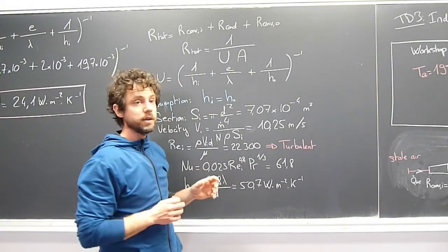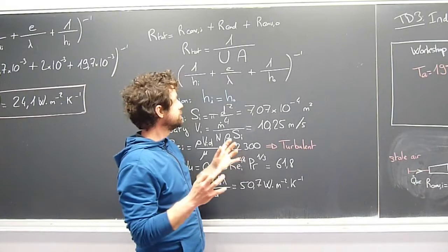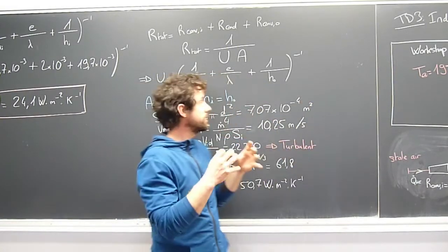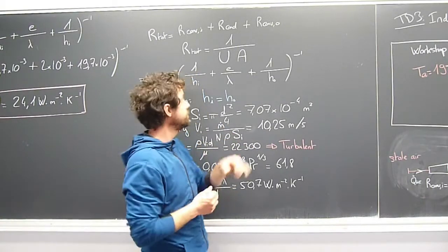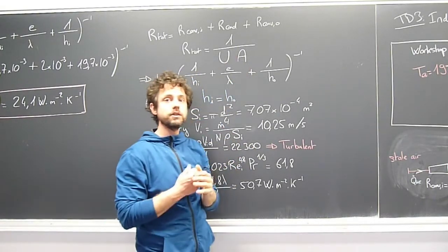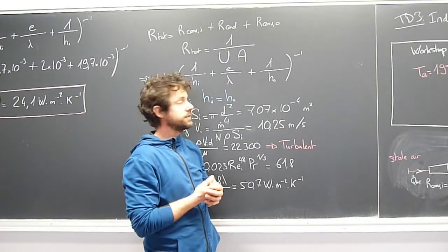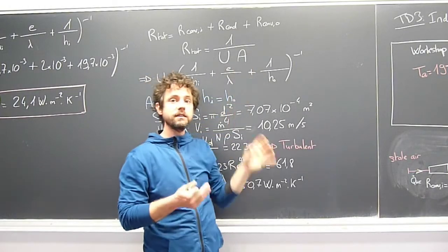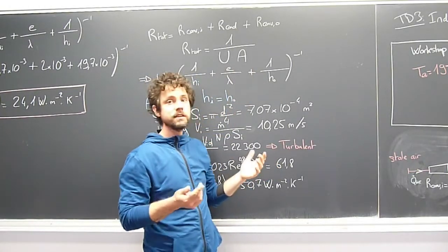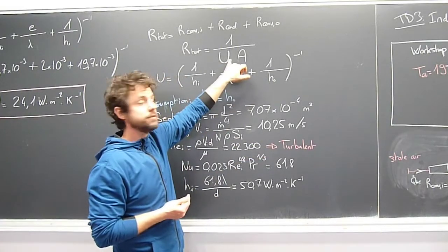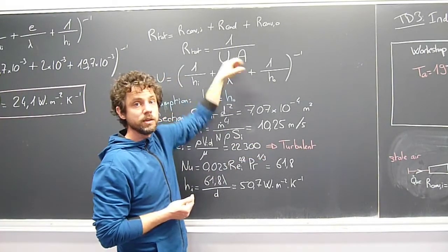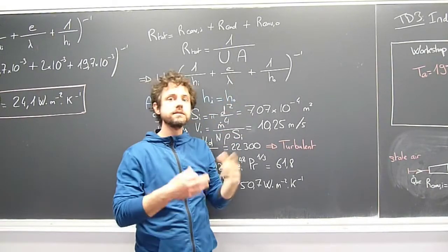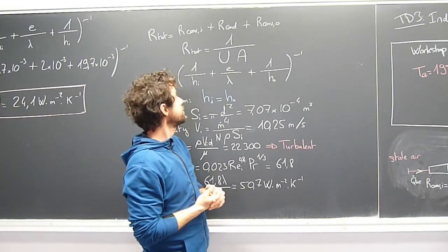And that's a way to put all the different types of heat transfer and thermal resistance into one single coefficient, U, that is homogeneous to a convective heat transfer coefficient. Here, because we consider that the inner and outer surface are equivalent, we only have one U. We don't have U_I and U_O because we consider only one single heat transfer area between the three.